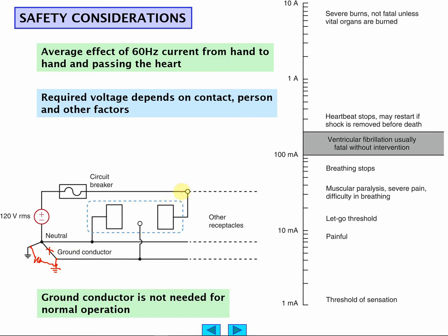So if you grab your hand on the hot wire and to the neutral, it's very dangerous for you. Hand here to ground is also very dangerous. But the neutral all by itself is also kind of dangerous, because it can have a potential that is not near your earth ground. And of course, you're standing here. You're standing on your earth ground. And this is literally a chunk of metal driven into the ground just outside your house. That is truly an earth ground. And you're at the same potential as that, where you are.